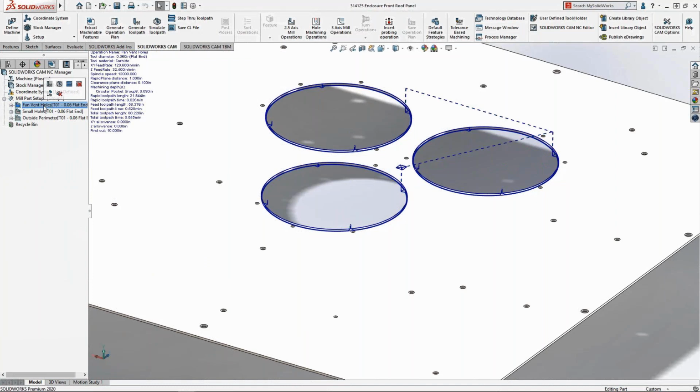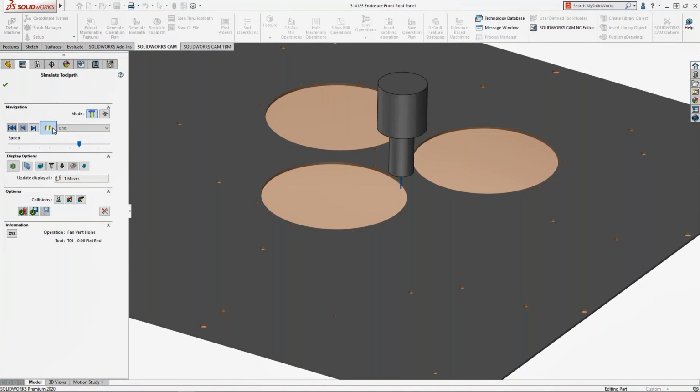confirm that the tabs were actually generated there. We can see it in the toolpath preview, and then also run a quick simulation of manufacturing, and we can see the tabs there. So the part's ready to manufacture once again, and includes having those tabs, which saves time from needing to do this operation in the G code. In addition to the tabs for 2D cutting operations, you can also use this same technique in milling on more